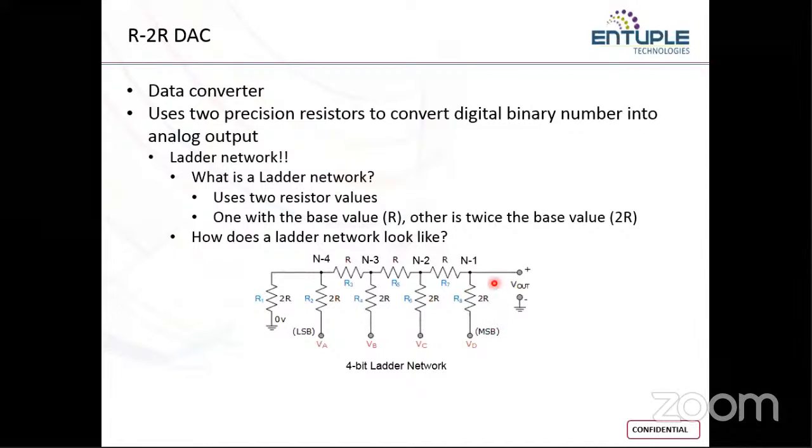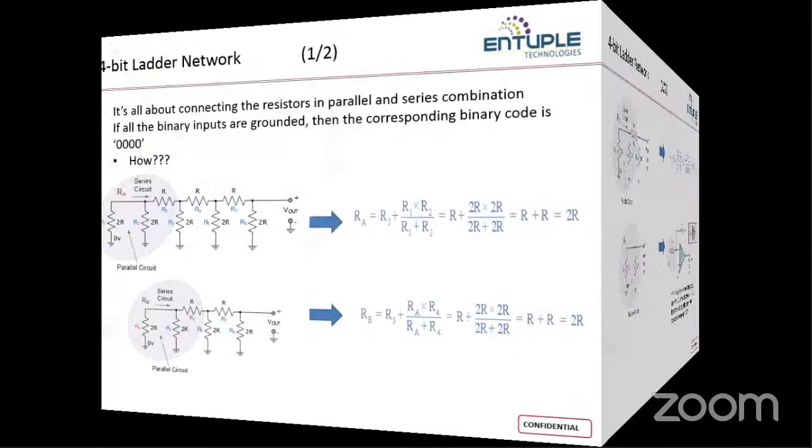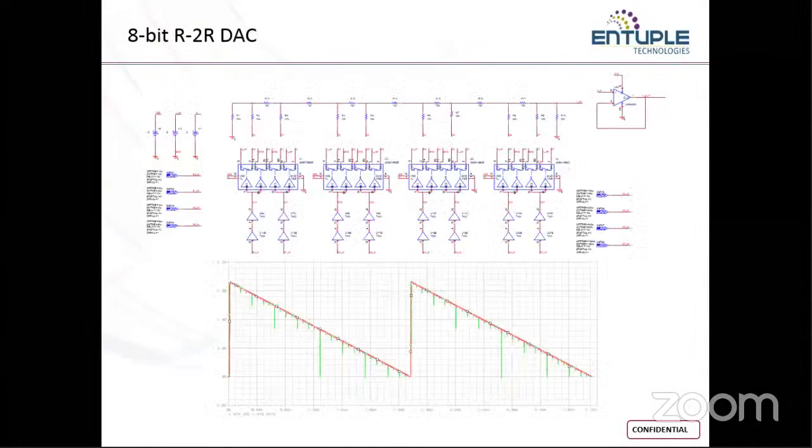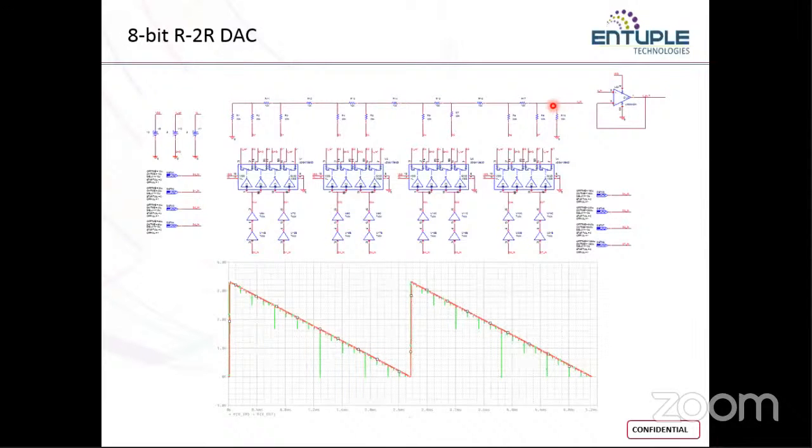So that is what we have done here in the circuit. We have included a resistance over here. So whether you get the equivalent resistance from this side or this side, the value of equivalent resistance will be the same. That has to be the case when you're talking about a ladder network. Similarly, you can also create a ladder network using capacitance, but it will be the other way, which you should be aware of.